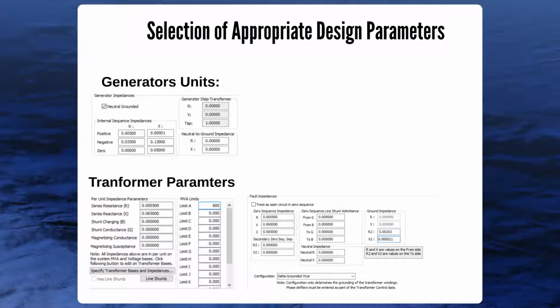These are impedances that are required for our various devices to protect them from any faults. If you note, a delta grounded star selection was made for our transformer for the sole reason of not allowing a fault from the system transmission line to reach back into the generating unit. We all know that that is detrimental to the system.